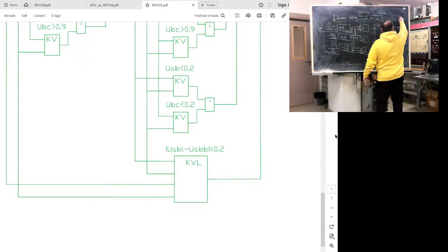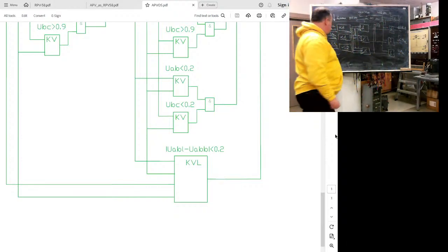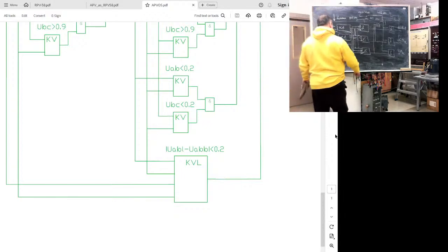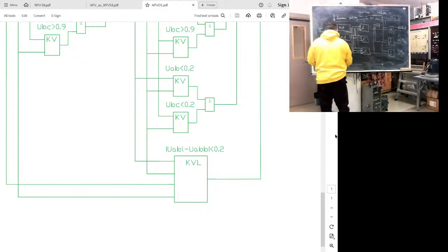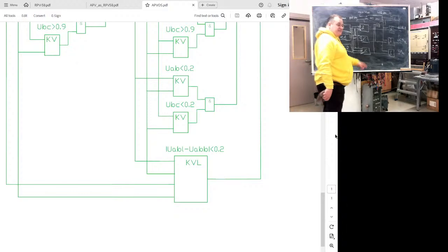This creates the signal disconnect O. It acts as a three-phase disconnection. So if we have second stage or we have a line-to-line fault, all phases will be disconnected. So the key moment is selectors and logic allowing single line operation, it's disconnecting a single phase. And auto reclosing will be performed on the second stage.